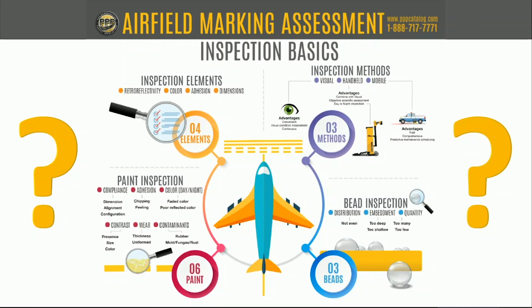You want to make sure that you're not flooding those beads with the light from the camera, because you can have a yellow line that looks white. But it may not be really as bad as it looks. One of the things that we do in the roadway environment a lot of times is, rather than use the flash on the camera, I'll hold the camera up, suppress the flash, and then put a flashlight around its lens and aim toward the marking.